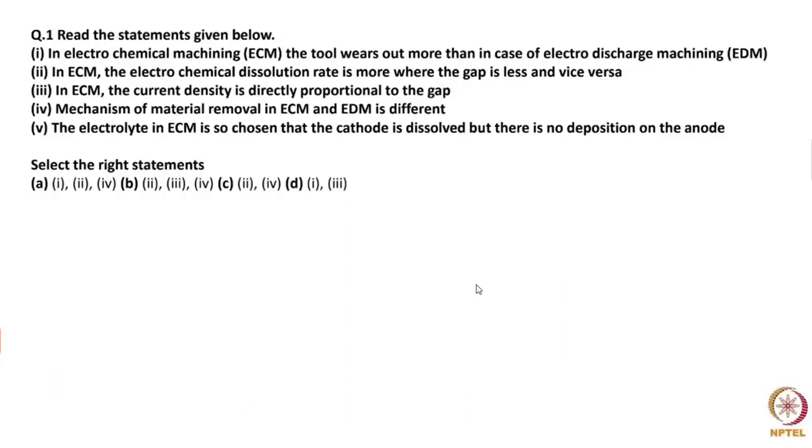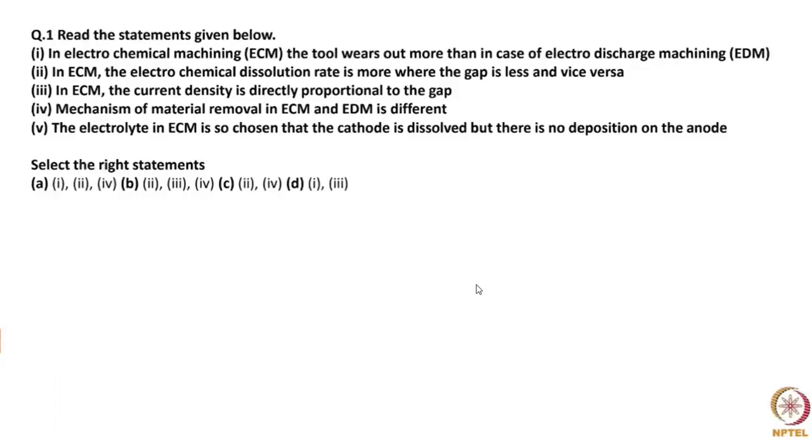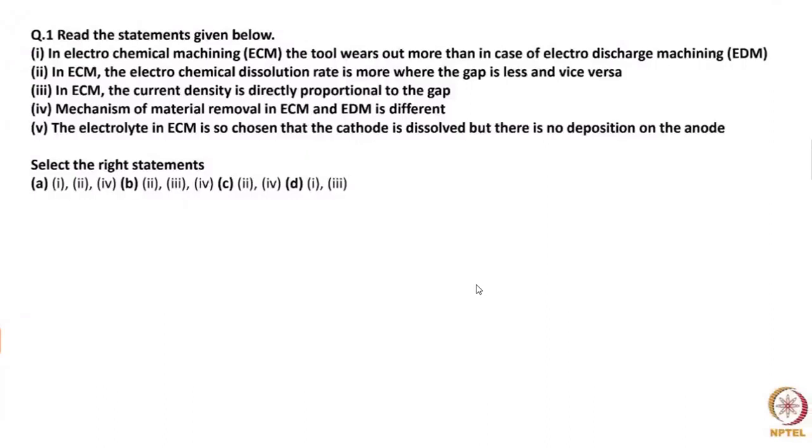By choosing an appropriate slurry, we can induce some chemical reactions and aid in the dissolution of the workpiece material at the surface. And through the cavitation action of the expanding and the contracting volume of the slurry in between the tool and the workpiece surface, we see that the debris or the materials which has been removed from the surface in the form of small pieces need to be evacuated from that region to ensure a good feature, with an appropriate standard of the feature and appropriate surface finish also.